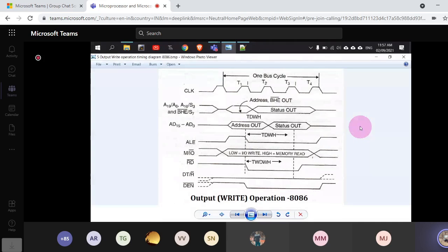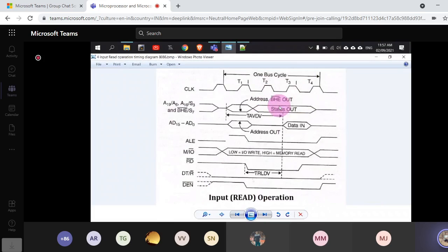I mean, there could be simple questions in your examination like this timing diagram is given. Identify what is going on inside the microprocessor. So this name will not be given to you that this is a write operation. So you should be able to see whether it is a read or write operation. So you should be able to see that in T1 state, the addresses are getting latched. So what is going on inside the microprocessor, it can be told by its timing diagram only. So you should be able to at least read a timing diagram properly, right?